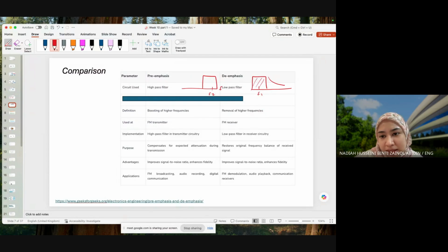So this part gets attenuated, this is not really happening much, this is amplified, and this is attenuated because it doesn't let these through. A low-pass filter favors low range frequencies, which means the high range frequencies will be attenuated at some point. They call this a low-pass filter because it behaves like one, even though it's actually a de-emphasis. De-emphasis is much more technical than a low-pass filter.